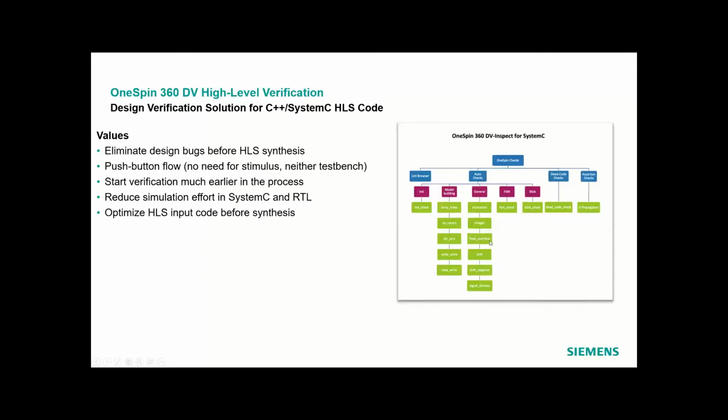We also support fixed overflow, shift negative, signal domain. We can also check the FSM table from the SystemC design, stuck or toggle checks, dead code or unreachable code, and also X propagation.